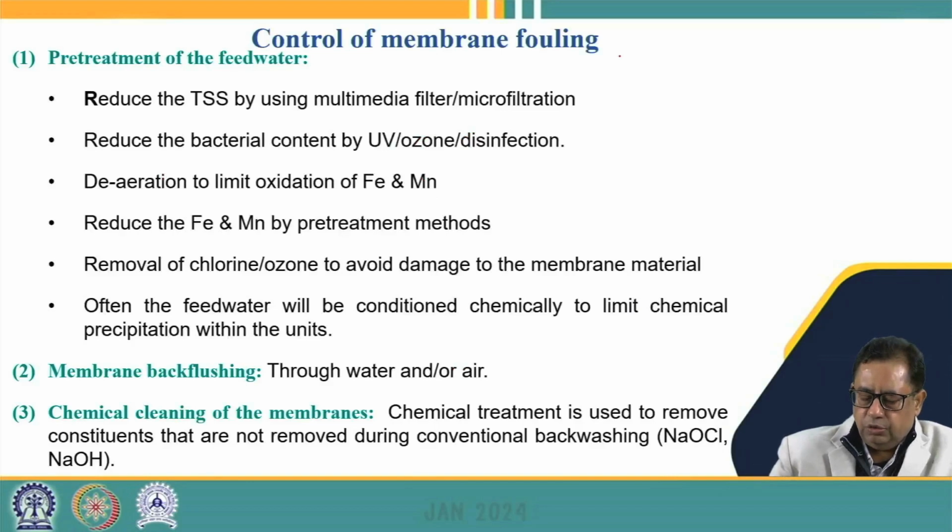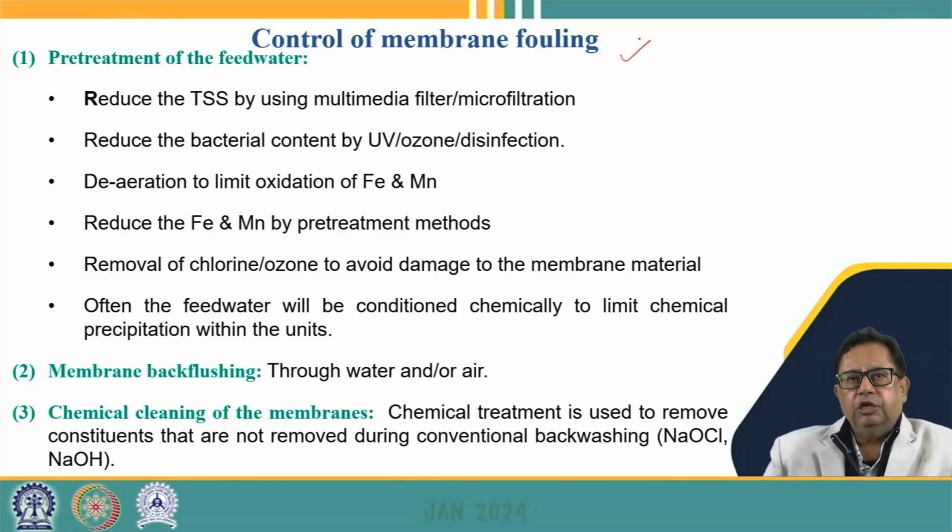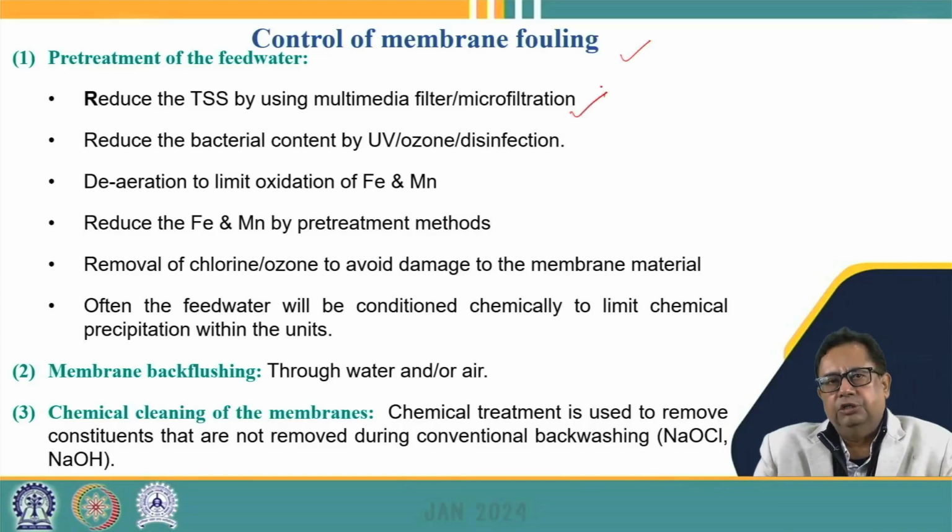So how can we control membrane fouling? We have already talked about the pre-treatment of the feed water. So how can we pre-treat the feed water? That is the matter of concern. We can reduce the total suspended solids, because if we have a very high suspended solid concentration in the feed or influent, this may lead to blocking and clogging of the membrane surface